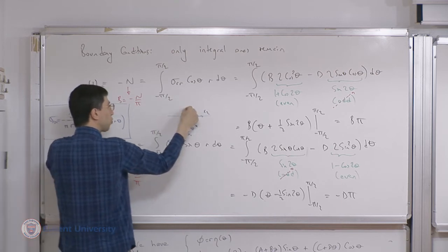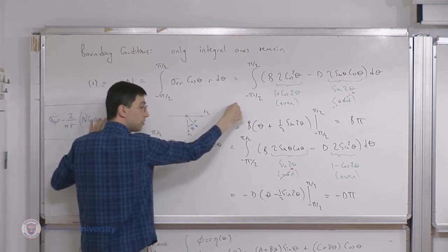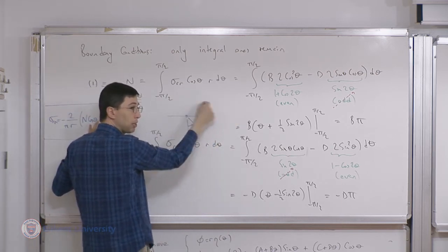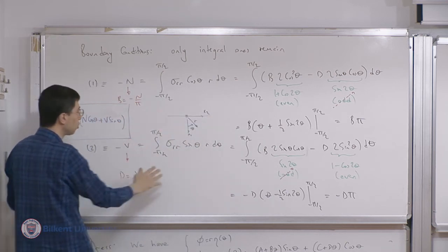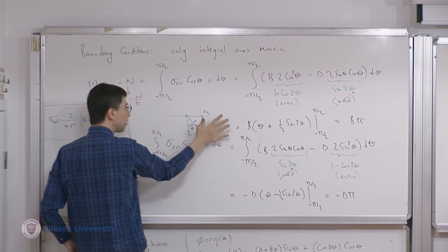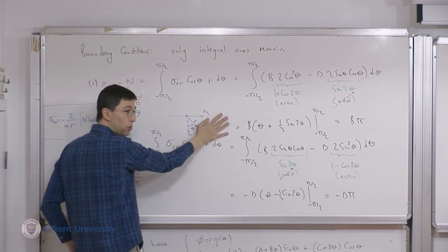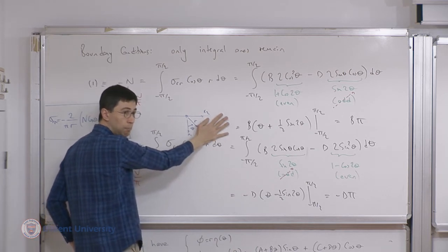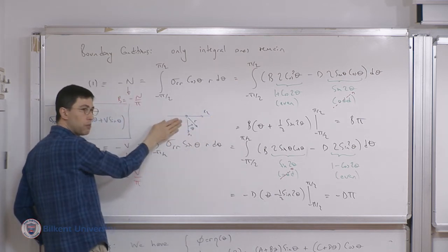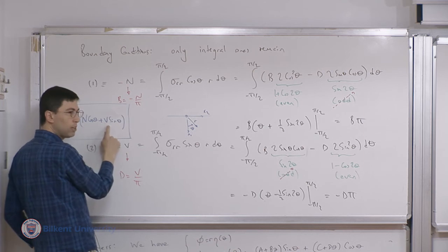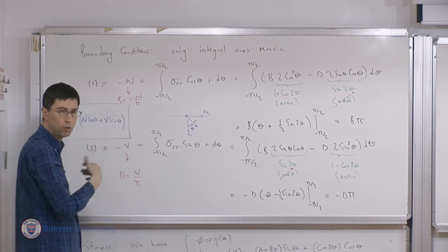And behind, I'm sort of pulling on the material that is lagging behind the point of application of the force. Minus minus makes a plus, so it gives me a tensile force. So no matter what you do in this setup, in this quadrant, you're going to have a compressive stress. But in this case, depending on the relative magnitudes of N and V, it could be either compressive or tensile.